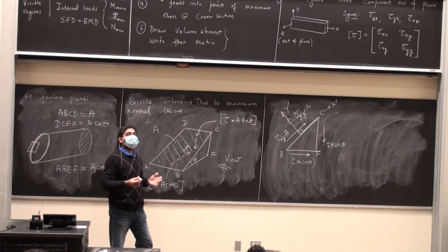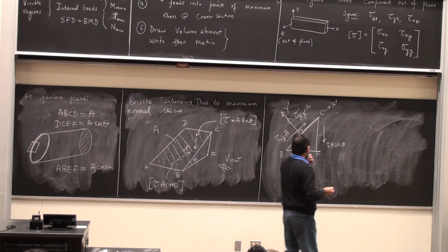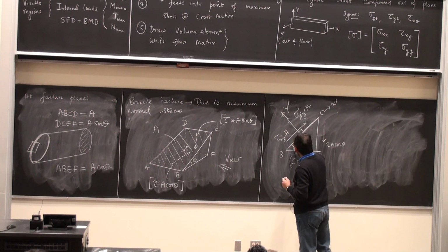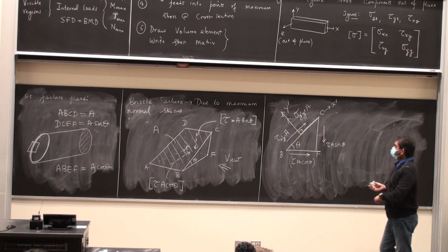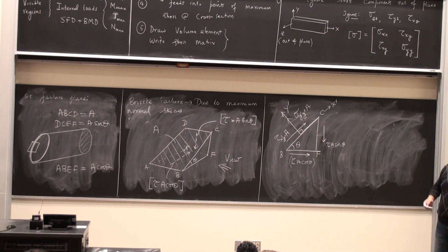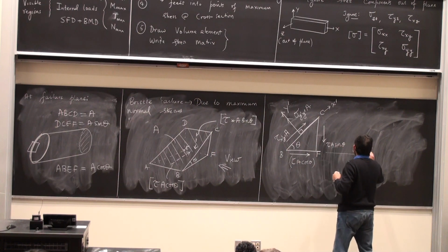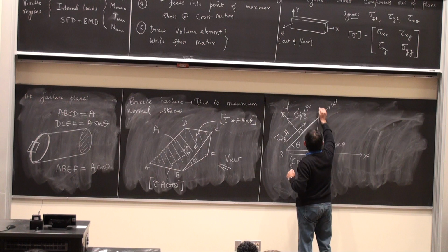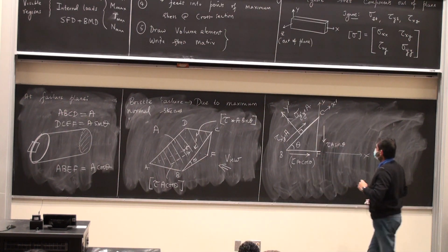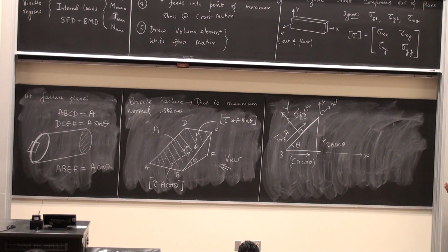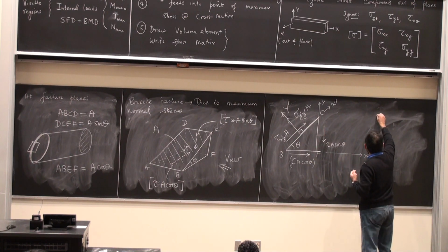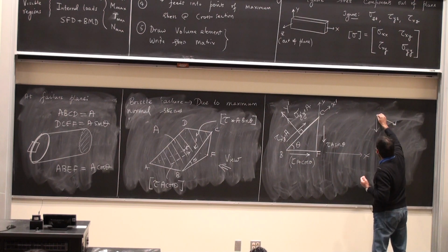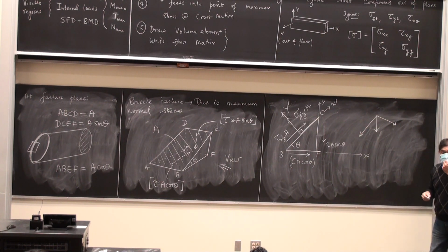It has to be in equilibrium, so I have to perform a force balance. Right? And so for that, I have to break everything into components. So I call this angle theta. This is the angle between the x-axis and the x prime axis. So this is the x-axis, and the y-axis is the vertical axis. Tau A sine theta, I have to break it up into components along the incline and perpendicular to the incline.